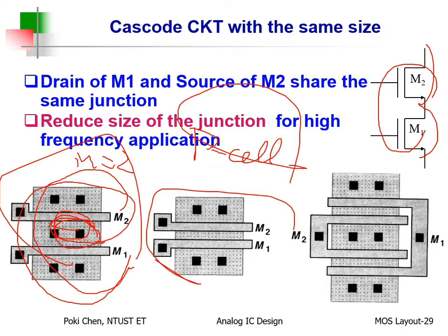Got it? You remove it, then it means the polygate of M1 and M2 can come closer according to the design rule. Alright? In this way, you not only save money for your boss, for your professor, but also you reduce what? Parasitics for this area. Got it? You can save money and at the same time enhance the performance. Why not? That's it.